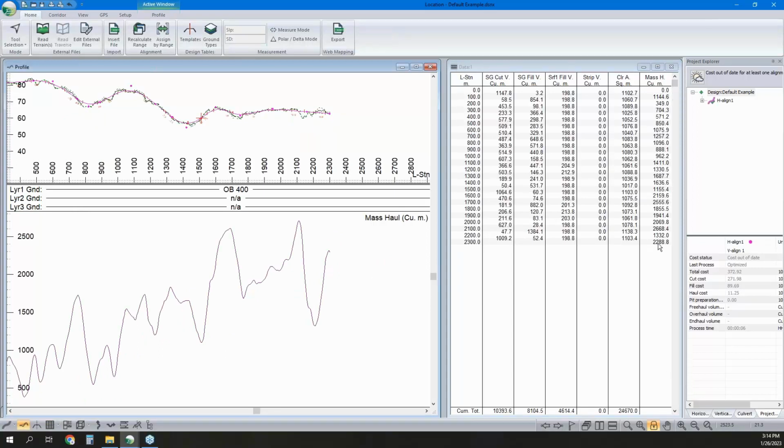We've got a 2,000 cubic meter surplus now. Our cuts and fills change because these are factored volumes that we're producing. And that's great to know, but it would be great to know while we were designing here so we could actually lift our road where appropriate so we don't have this surplus that we're creating for absolutely no reason and costing us more money.